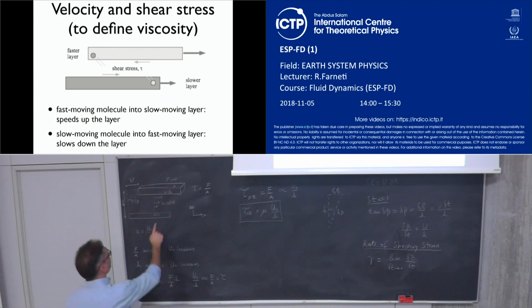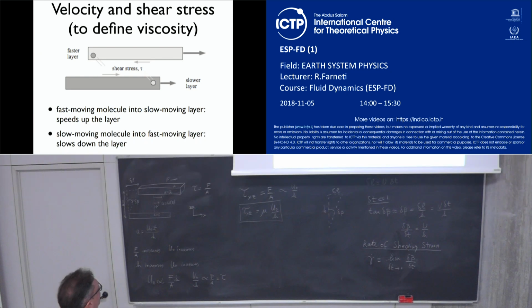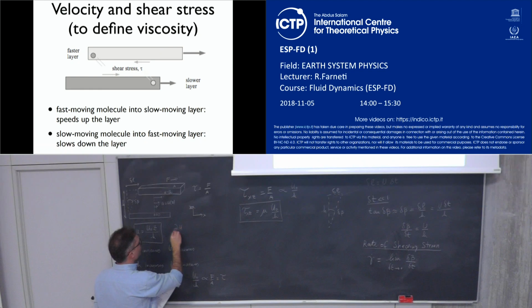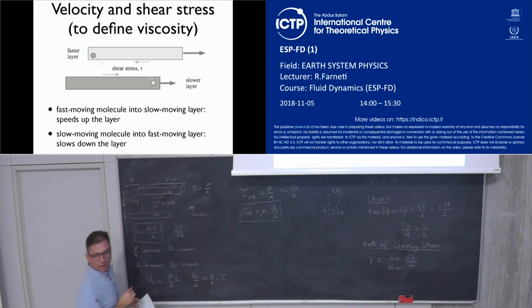Now remember we have a linear profile of u with depth, which was this. And so we have a velocity gradient, which is going to be du by dz in this fluid. U varies with depth or height in a certain way, du by dz. And in this case, because it's linear, the velocity gradient is a constant.